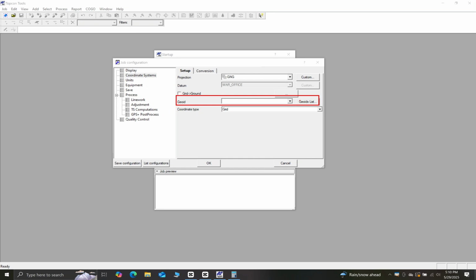Now most often than not, when we are doing our cadastral works, when we are doing our static survey, we use 2 receivers, and then we set one of the receivers, we use it as our base, and then set that particular receiver that we are using at our base on a known control point.